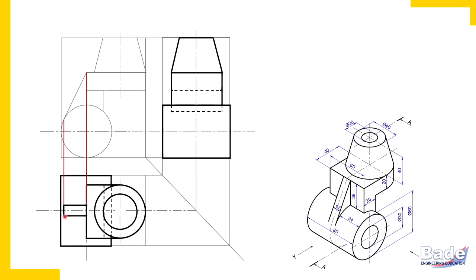But there is a mistake. Watch here, the earlier drawn 12 millimeter long thick line here, that should not be there because here there is no sharp edge. It meets cylindrical surface tangentially. So that vertical line must not be there. Check here how we showed the tangential joint. So I have removed it and show these small curves at the end of these two edges to indicate tangential joint. Okay, so top view of that rib is complete.